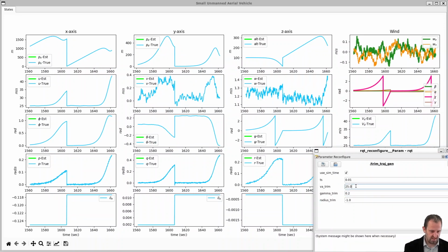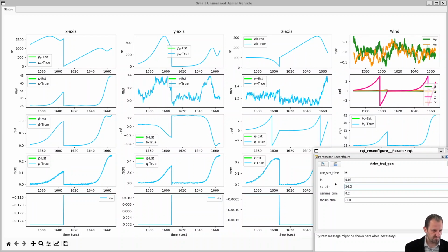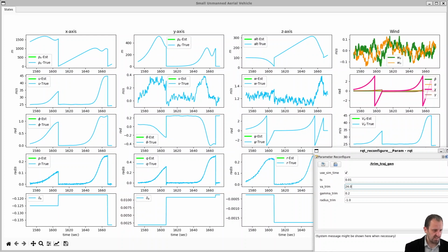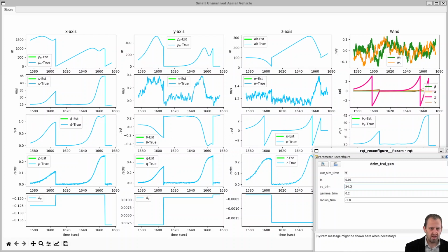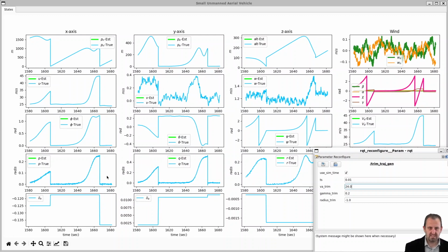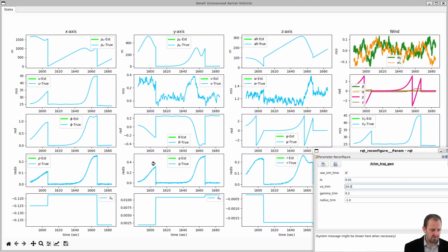So let's bring it back. Maybe we'll change the velocity to 24. So restart it. Okay, and you'll see again, that was just a hard reset to all of our states. So we start to climb linearly, and you can see we're getting close to these nominal values. So we've defined nominal states, which is where we reset the aircraft to, as well as nominal inputs.